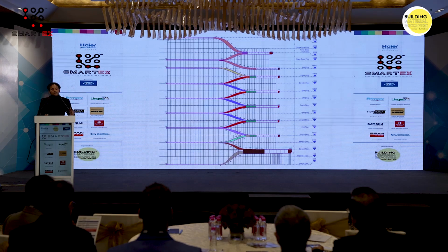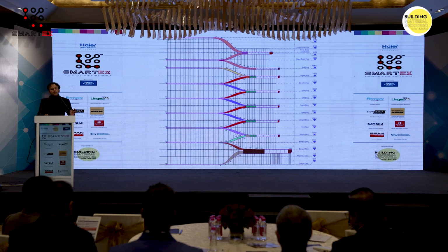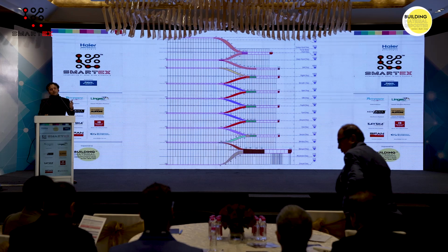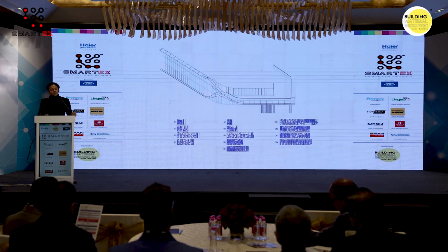Now coming to GRC, glass maybe I'll cover a bit later, but GRC was very critical because I've heard a lot of people complain that the finishing in curves never comes out good. The idea for us to use a GRC system in this case was because it's a mold-based system. We can control the mold, we can do digital fabrication of the molds, and the precision we can get is within plus or minus 2 mm. And this is what we're aiming for. This actually shows the repetition of molds. Red is the same mold, here blue, and then we have some non-standard molds which we're using.